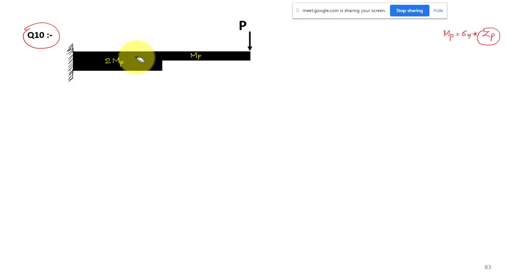So here, first let us find out the static indeterminacy. Static indeterminacy R is 0. It is a statically determinate beam. So for the failure, we need R plus 1 number of hinges, which is 1 hinge. So 1 plus a hinge is required to form a mechanism.